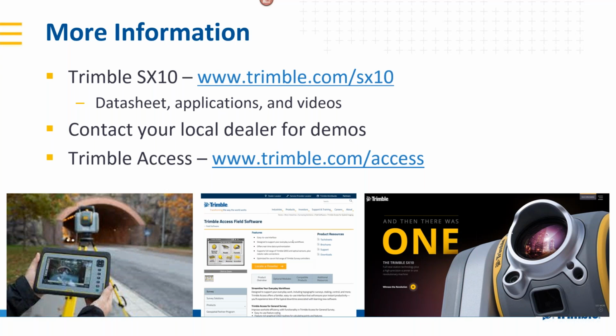I think it's either 50 meters or 100 meters that it gives the resolution to, but I think at 50 meters you're looking at around 1 centimeter, 1.5 centimeters, depending on the type of scan you do from the 4 options that we have. So we have the coarse, the standard, the fine, and the super fine.